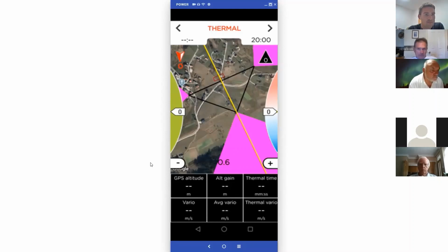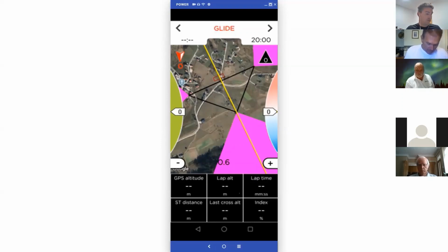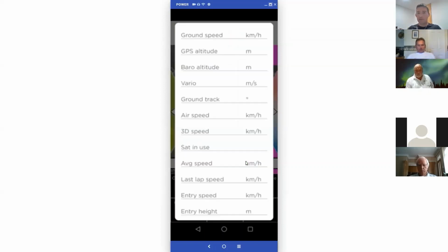So, some questions. David Woods, can you listen to the GPS altitude and speed on your Yeti telemetry voice announcement? Yes, you can if you set it like that. Then you have to set non-compressed data, just normal data, and then you can have on your Yeti announcement on your buttons to tell you altitude, speed, altitude, speed. So again, by pressing on the now box quickly, you get the list. And now we will go through the list.